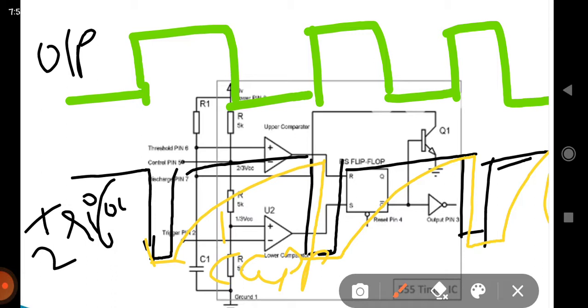Yes, this is in pin number 5. This is a capacitor charging and discharging curve we can see in pin number 5. Right, in the trigger we can see in pin number 2. The pin configuration of the output is pin number 3. This is pin number 3, pin number 2, pin number 5. These are the graphs of the monostable multivibrator.